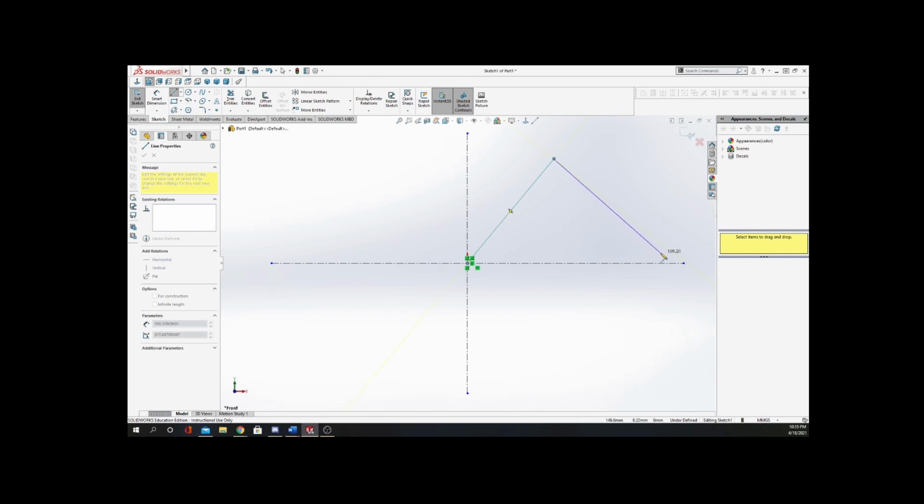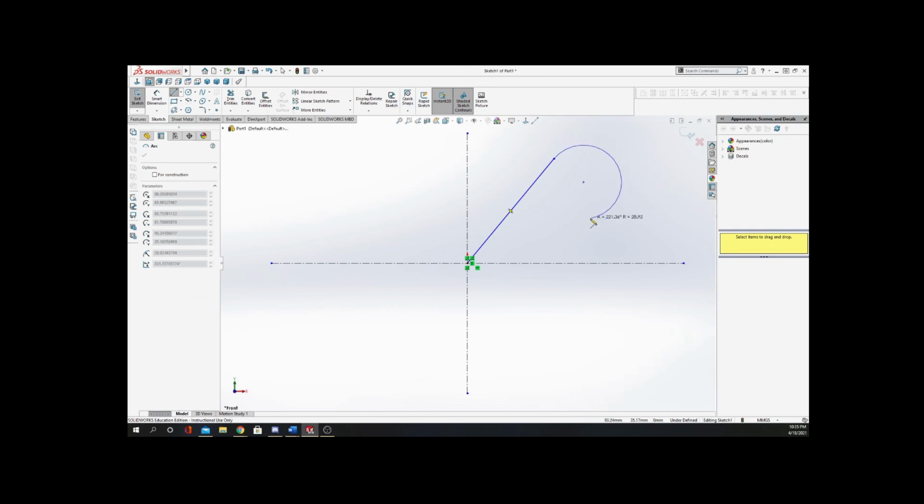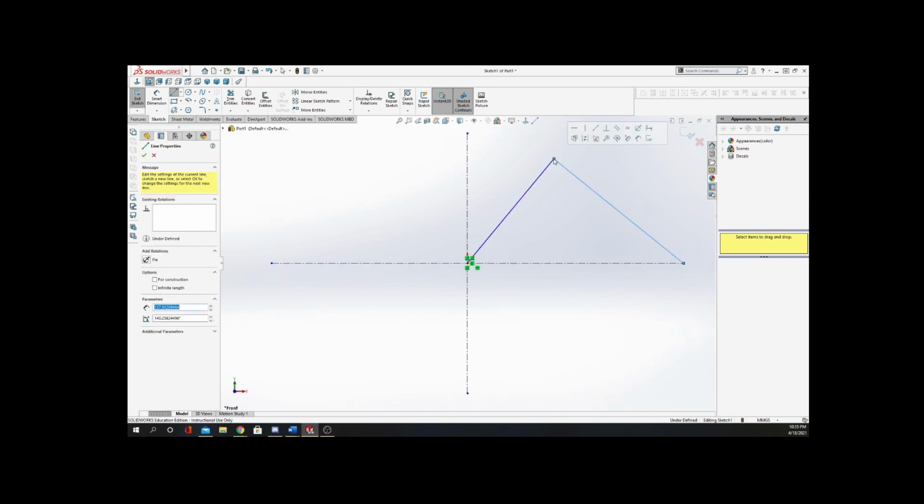And then you can see that it gives you a few options here, like some prompts. Right there, it's telling you that that's going to be a right angle, so a 90 degree. When I went back to that point, it then gives me an arc off of there. And if you go back to it again, it gives you a straight line. So let's do our straight line, and we'll draw that down to this point here. And we can say escape.